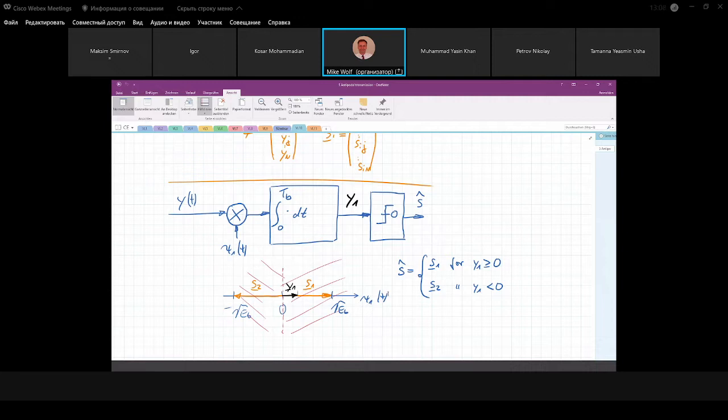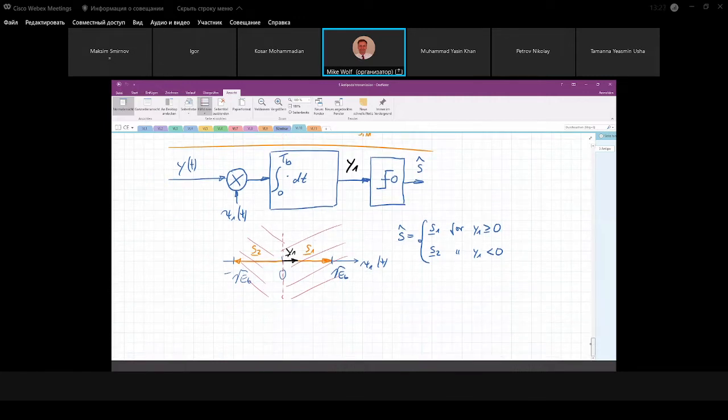And now we just want to proceed, and I will show you that we have an alternative implementation of this detector. Instead of the correlator, we can use a so-called sampled matched filter, which has exactly the same performance. If you implement this as a filter, you can really see what happens in practice.